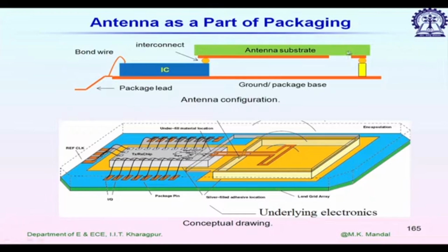and right hand side you can see we have a support for the substrate, it can't hang in air, and below the radiator we have air cavity that will improve the efficiency of the antenna. This below structure you can see we have a folded dipole antenna fed by coplanar strip line, and we have one more guard ring here backed by metallization, metal ground. It forms like one cavity.